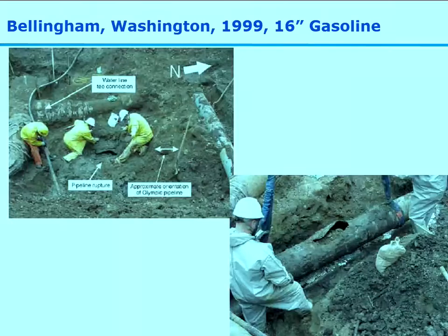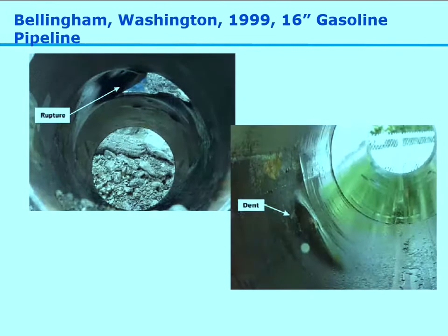And the damage was evident on the inline inspection for the pipeline, but the operator didn't know how to interpret the damage and didn't actually dedicate any effort or pay any money to get experts to assess it. So the pipeline accumulated quite a lot of damage, which you can see on these photographs. And then the combining event, you often find with serious incidents there's more than one cause of failure.